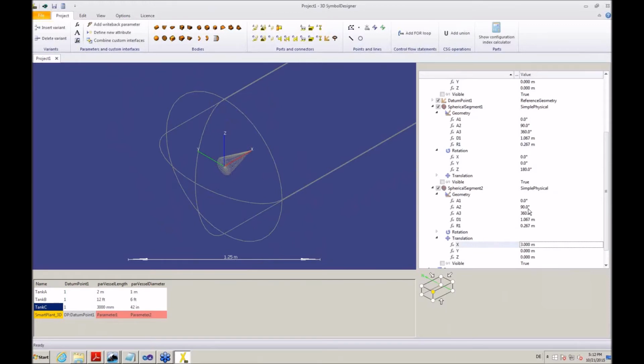So everything you have seen so far could be done by junior engineers. You just need to know a little bit about engineering. Basically, you look at the drawing, you decide what parameters to use and what bodies you want to place in here. The final steps to get this into Smart 3D should be done by senior engineers who know about the Smart 3D catalog. It's the parameter mapping and selection of the target nodes in the catalog, and of course, at the end, modification of the bulk load files.